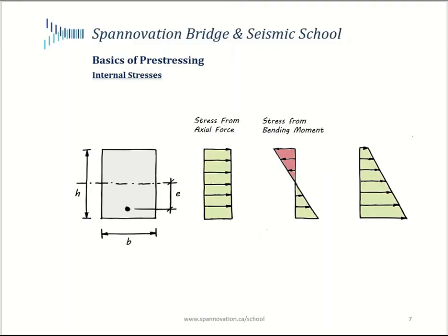Okay, so now let's look at the internal stresses due to prestressing at this concrete section right at midspan of the simply supported beam. On the previous slide, we realized that at this section there is a net compressive force P that's acting at the neutral axis, plus there is a clockwise moment that's being applied on the section. Those were the equivalent force effects we derived on the concrete section. So our approach to finding the stresses would be to derive stresses from these forces and then add them up to get the stress effects.